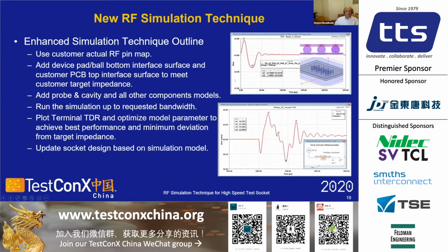Yeah. For the socket, for coaxial or impedance control socket, the anodizing is proprietary to the supplier. We have a proprietary property that we use, not really just anodizing, it's a coating. It's a high speed coating and high temperature coating that has a good property for signal integrity. So this is proprietary information from the supplier.